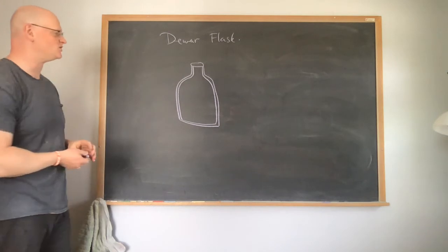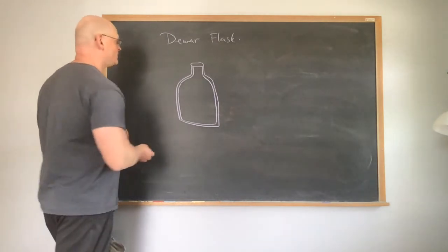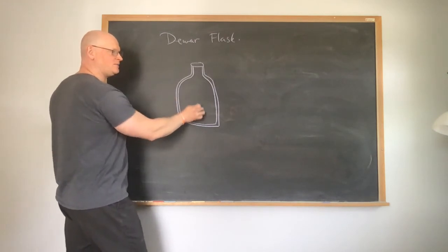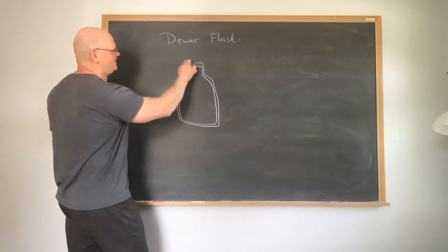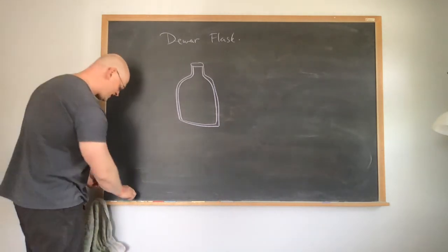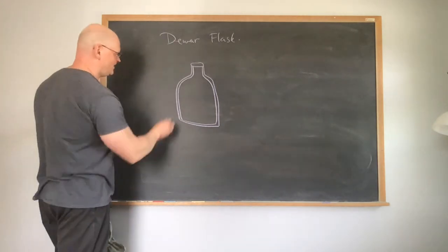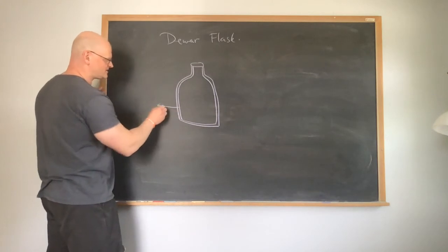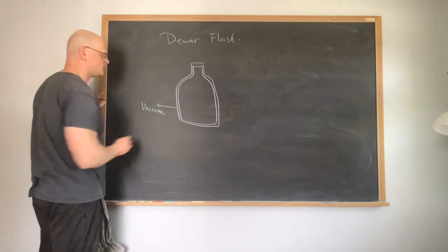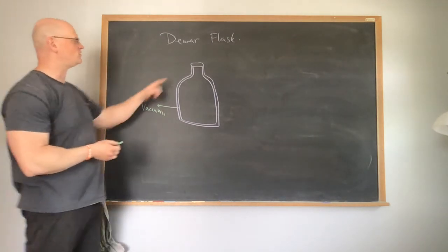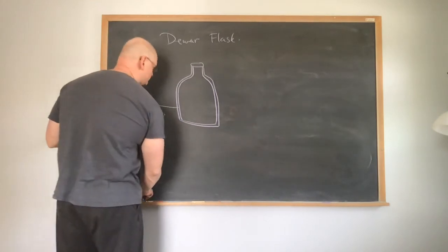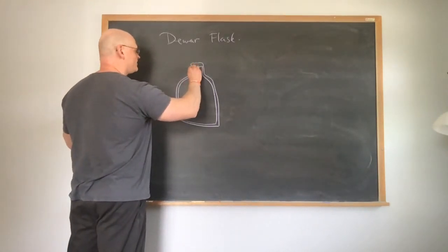You don't want it to become lukewarm, right? So typically what happens is there's a layer between the inside portion, which is where you're going to keep your tasty object, and the outside portion, which is going to save it from the wall. Now, here, there's a few conditions. Inside of here, you usually try to vacuum out this inside wall. So you want to make sure that that is a vacuum, so this has to be airtight. And then you also silver the walls on the inside.